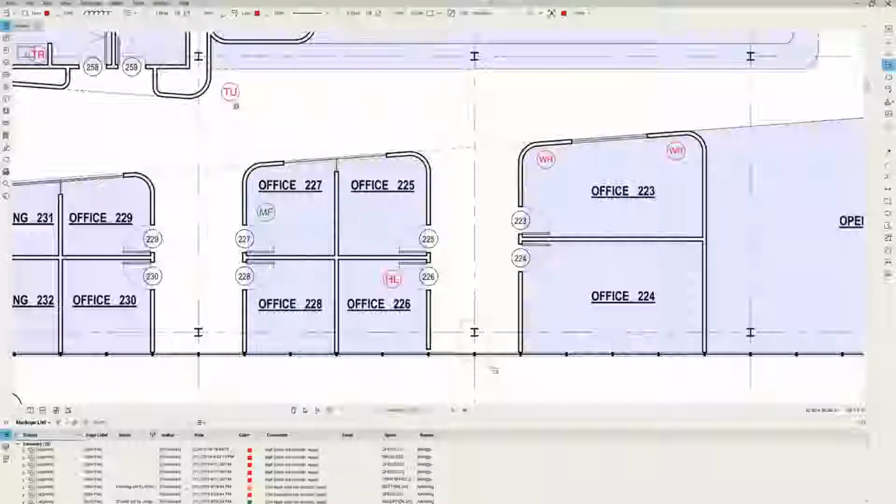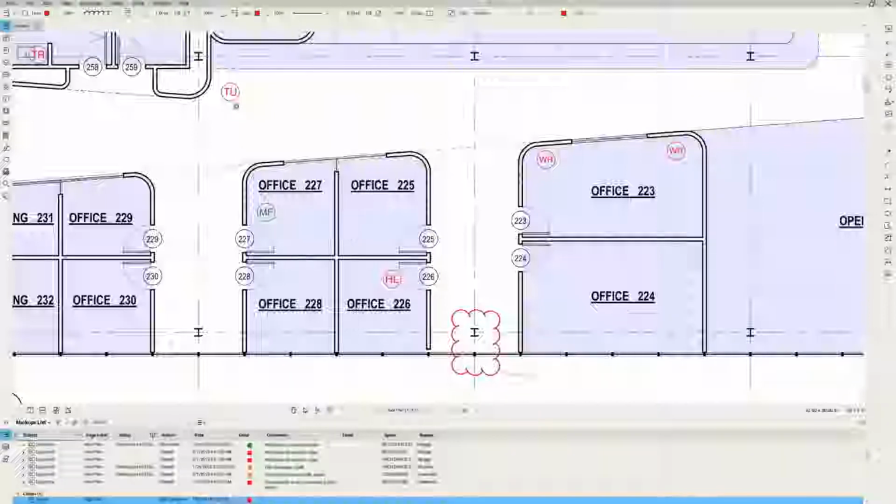And I'm going to put the Cloud Plus right there. Now, if you have a tool chest that has these already in there, that's fine. I'm just using something straight out of the box, and I'm just going to call it RFI. I'm going to start off that it's RFI 1001. So I've created the markup. I know that's the spot I want to ask the RFI question.